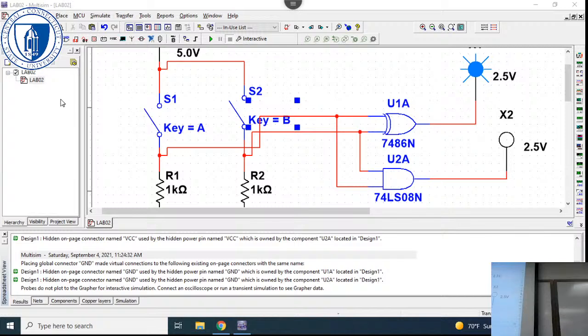Fahim had a slightly different approach to those, and he's got a two-position switch. One of them's going to the ground and one of them's going to +5. That's okay. But if you've just got a single position switch, I recommend using either a pull-up resistor or a pull-down resistor.